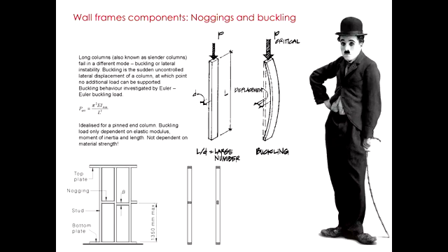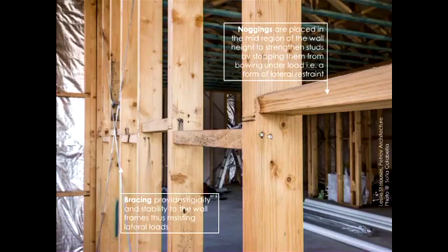So these images are taken from that Australian standard, the 1684.4, which tells you the spacing between studs, which tells you at what height you need to place the noggins. So everything is in there. You don't have to guess anything. It's all given by the standards, all right? The way it looks is this. All right, so more or less they are placed in the mid-region of the wall.